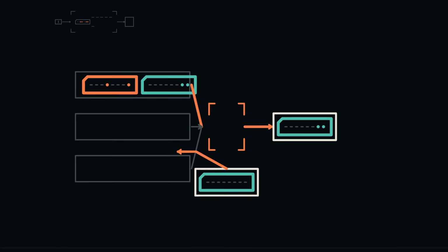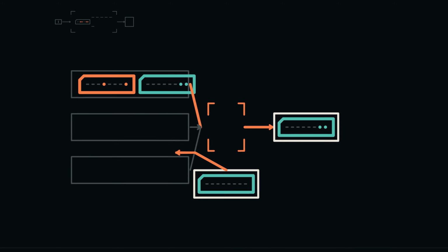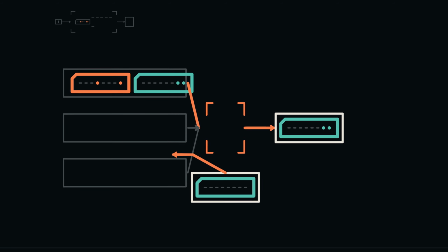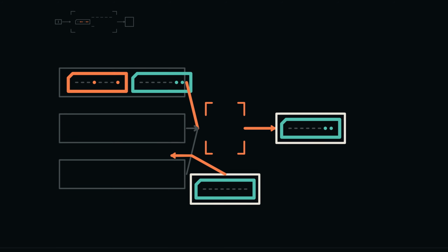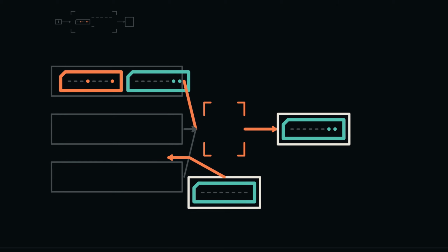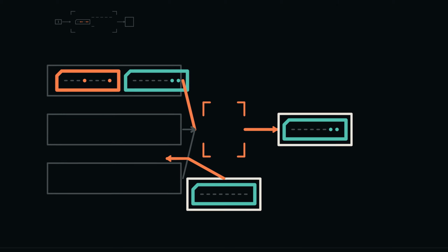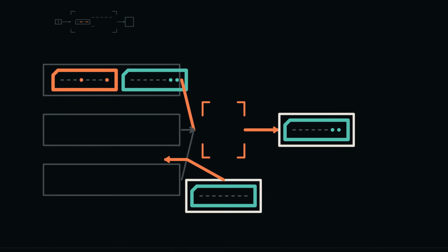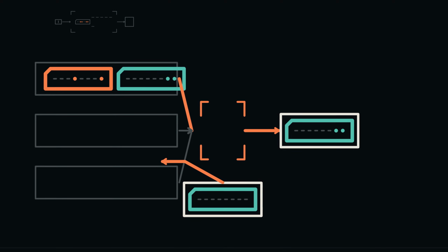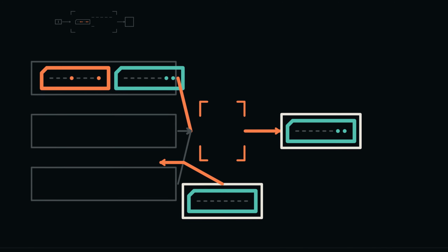The program counter, or PC, preserves the address of the next instruction byte. Ordinary progress advances it, jumps and branches may replace it. At reset, SE8 sets PC to the program's origin. The controller copies that address into MAR, memory returns instruction bytes, and PC advances. The visible PC to memory route is a selection promise, not an arrow meaning the program flows as one object.